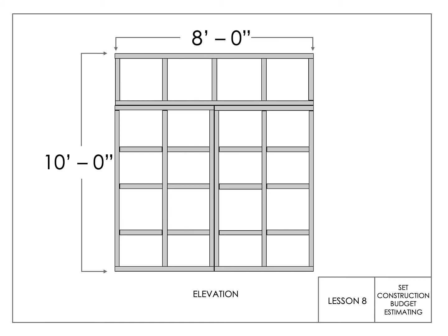So regarding the entire 8 feet by 10 feet wall elevation, there are a total of 3 flats with material requirements. 2 of the flats are the same, so just double these dimensions. To estimate the number of materials needed for the header, you could divide the measurements from a full 4 feet by 8 feet flat by 2.